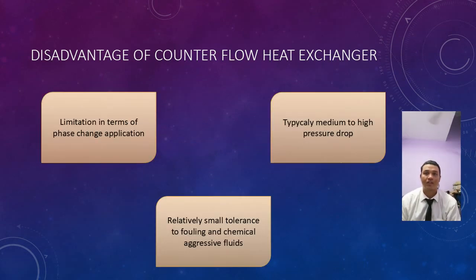After that, the disadvantages of the counterflow heat exchanger. Number one, limitation in terms of phase change application. The second disadvantage is typically medium to high pressure drop. And lastly, relatively small tolerance to fouling and chemically aggressive fluids.